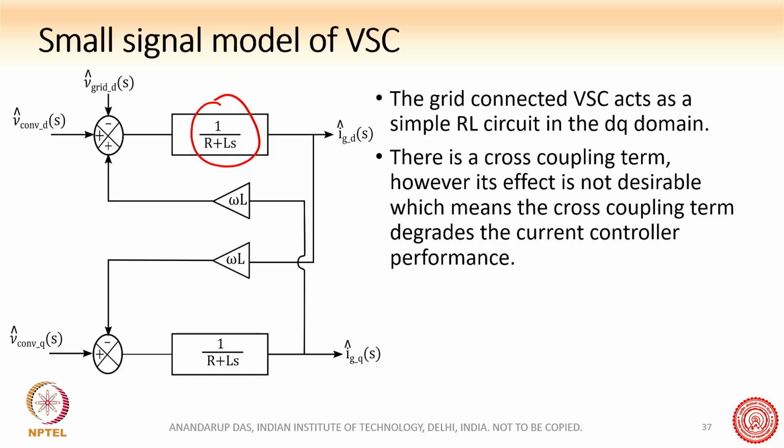So there is always a delay, but this delay we have neglected, and there is a reason why. The reason is that modern day power electronics and modern microprocessors are very fast. For example, nowadays MOSFETs, or even silicon carbide MOSFETs, take hundreds of nanoseconds to turn on, much less than microseconds.